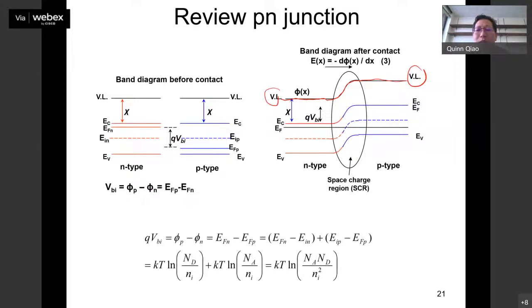The only thing, if you want to see a change, that probably changes inside the junction. Look, if this is a junction, you see now the Fermi level is here. You can claim my work function changes in these regions. In this region it changes, but outside that, nothing changes. Why does it change in this region? Because you bring extra charge there. Did I answer your question? Yes, sir, I have got my point. Okay, great.